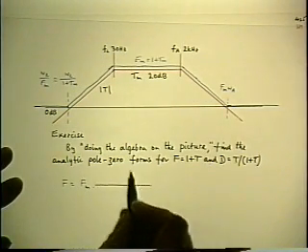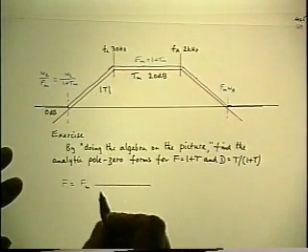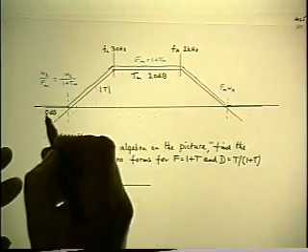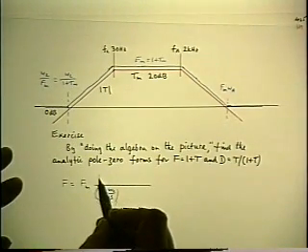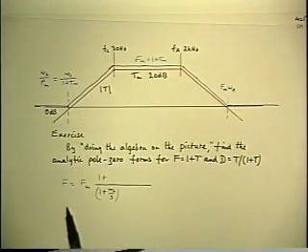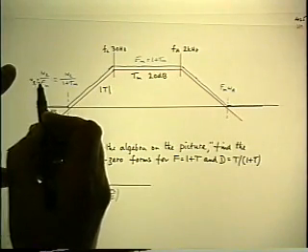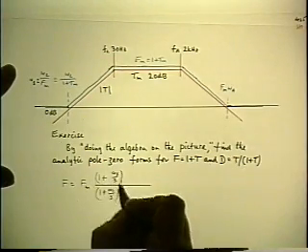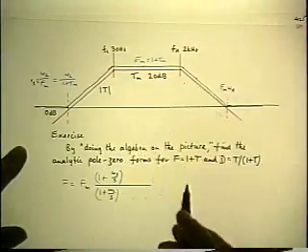And as you look down in frequency, first you're going to encounter a concave downwards corner. So that's an inverted pole at omega 2. As you continue to look down, you have a concave upwards corner. So that's an inverted 0. Now I could write this value out here, but instead I'll define a new frequency. I'll call this omega 3. So I'll write that as omega 3 over s. That's the inverted 0. And looking up in frequency, this is exactly the same as we had previously.